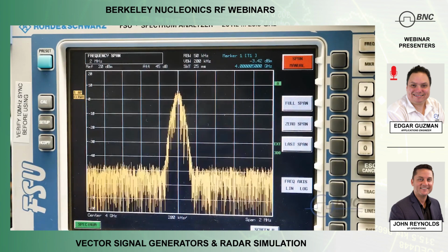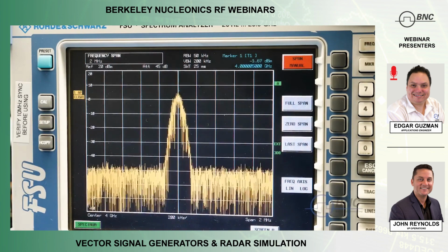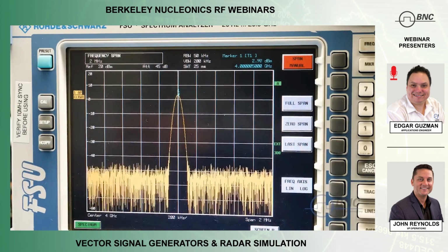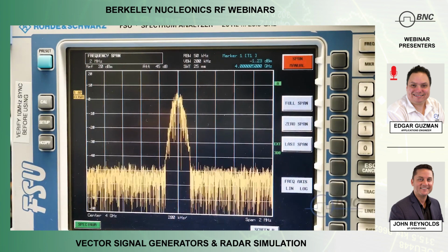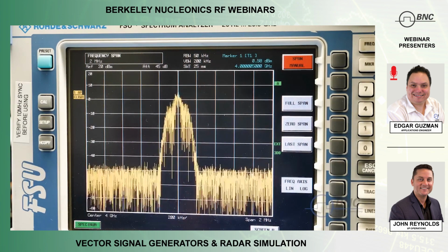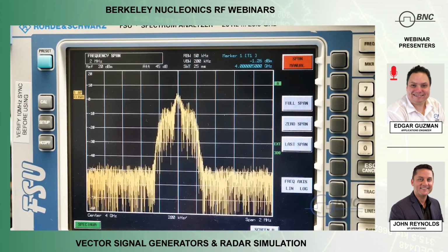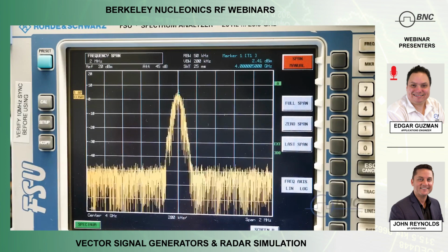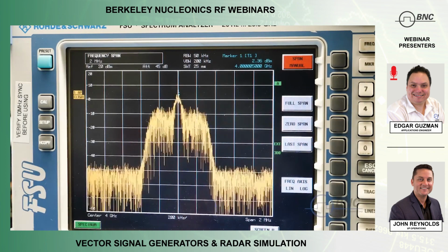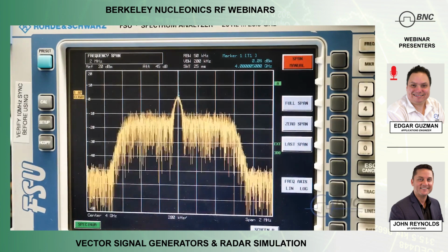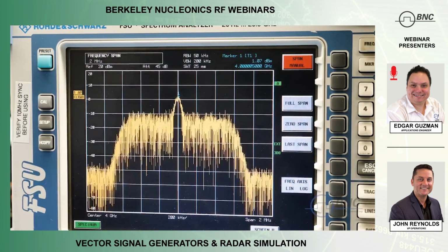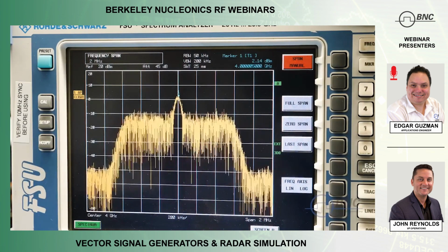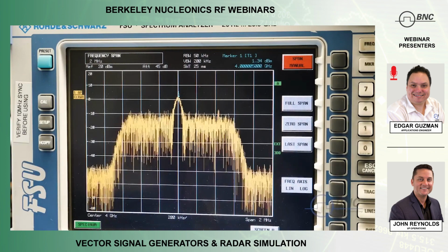And I'm going to zoom ahead a little bit where I actually introduce noise to the actual frequency of the signal itself, as opposed to just being kind of around it. So I'm giving you an extremely noisy pulse there with a lot of peaks, and the frequencies around the center 4 gigahertz frequency. So it's only, I believe, 10 kilohertz around is what I'm doing. So it's not that wide of a range. But yeah, here I'm doing, this is 500 kilohertz, I believe, given our frequency spans 2 megahertz right here.